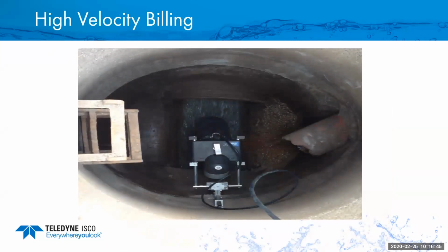This is what the sensor looked like when they went ahead and installed it. Stainless steel mounting brackets, easily installed. There's 2 bolts that hold that bracket on there, and the sensor just slides right in, locks in place. The laser has a built-in accelerometer like your cell phone, so it knows the X-Y axis. It knows if it's surcharged, went underwater, if something shifted, it will tell you that as well. So very intelligent design as far as knowing where that sensor is.